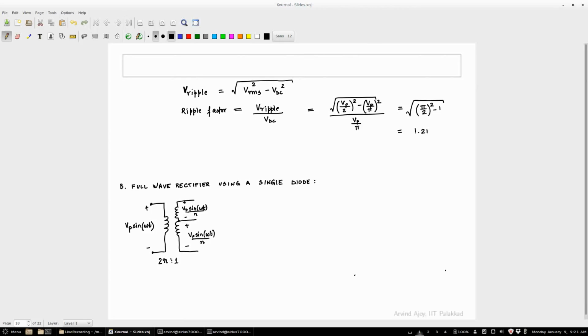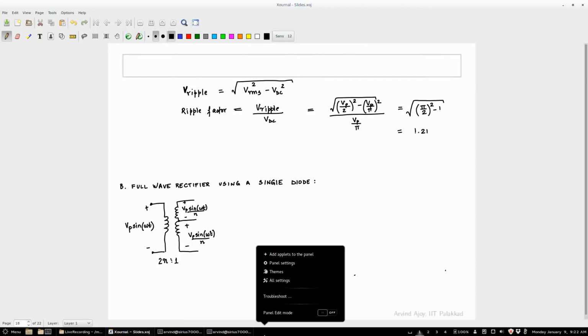Okay. So basically, in a regular transformer, you have one primary winding and one secondary winding, right? And in the secondary winding, you have access to both the ends of the secondary winding. Now, the secondary coil is wound on a core, right? So say at the middle of that secondary winding, you solder a third wire. So now you have 3 leads that come out from your secondary winding, right? One is the beginning of the winding, the other is the end of the winding, and you also have access to the midpoint of the winding.